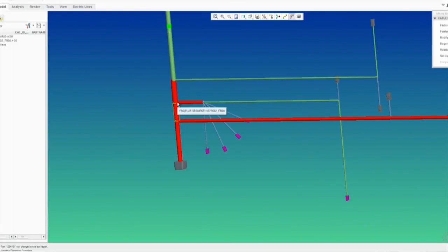Right, so when we give the models to the harness manufacturer, we also give them a copy of our custom tool software that runs inside of Creo Parametric, just like I use. It's just a different mode, as they're in the drawing mode. So they extract the information how they want to extract it. Most of that, I make the harness manufacturer responsible for. They look at the spreadsheets, and they can look at the engineering drawing that they're legally bound to build to, and they'll see that the lengths are the same at that point.